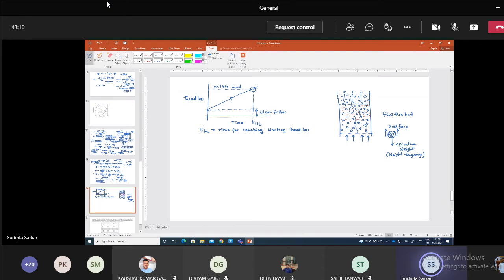But after this, we again pass the water in the cycle. When you reintroduce the water, initially, during a certain time period, some of the particles which are still at the bottom, which could not find their way all the way up, cannot leave. So when you re-enter the raw water, initially you get some bad water coming out of this.